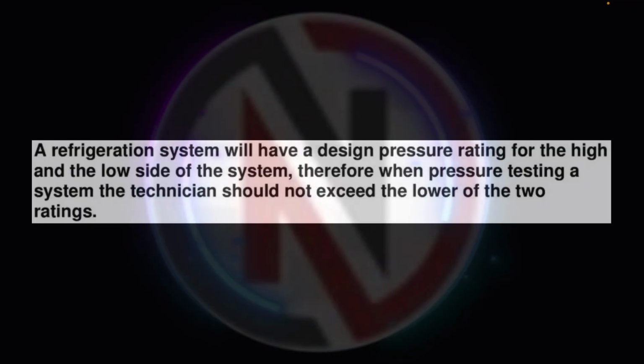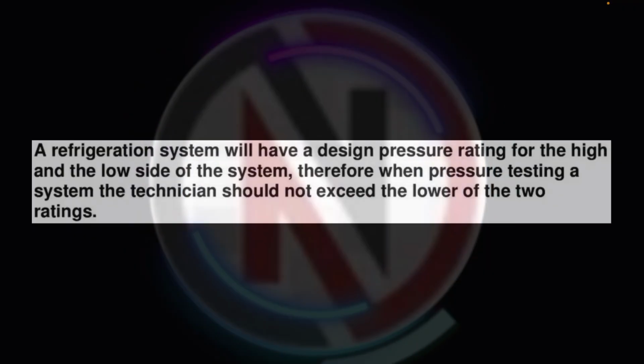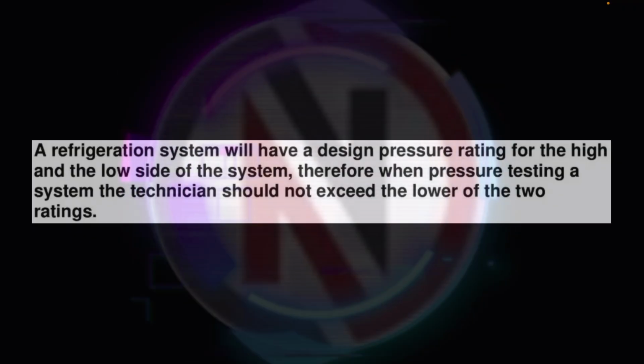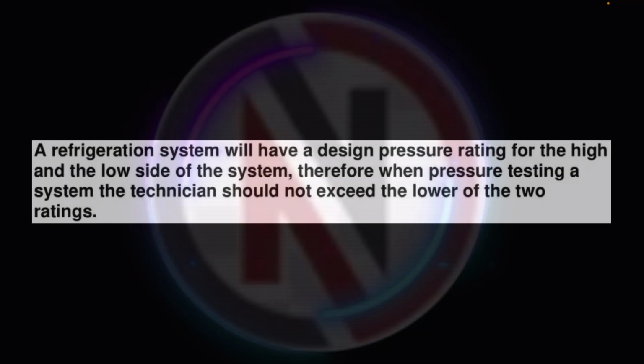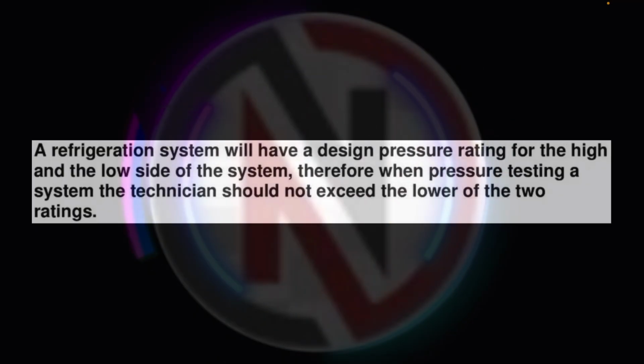A refrigeration system will have a design pressure rating for the high and the low side of the system. Therefore, when pressure testing a system, the technician should not exceed the lower of the two ratings.